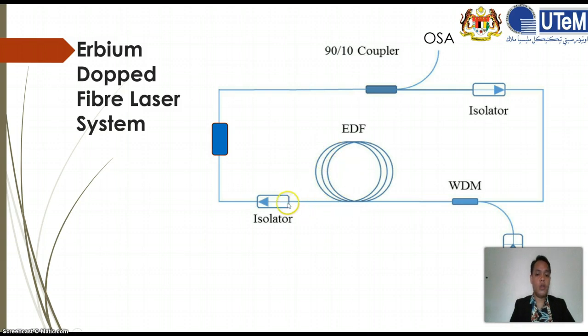After that, the signal will go through the isolator. The function of the isolator is to prevent backscattering of the signal, to take care of the pump LD, because the pump LD is a sensitive machine. Whenever there is a backscattering signal, the machine will be broken. After that, it will enter this box, which represents the optic fiber ferrule. At this optic fiber ferrule, it can be dismantled, so the Q switch or the SA saturable absorber film can be put in between the cavity. This is where the film will be analyzed.